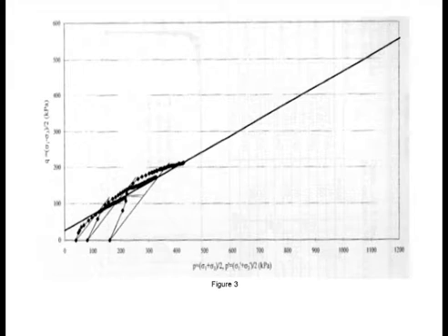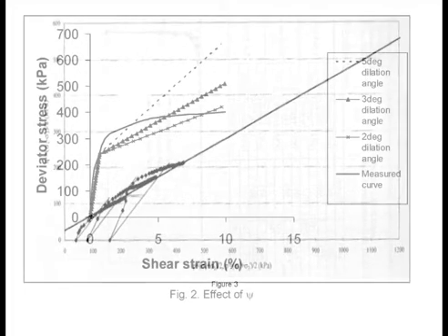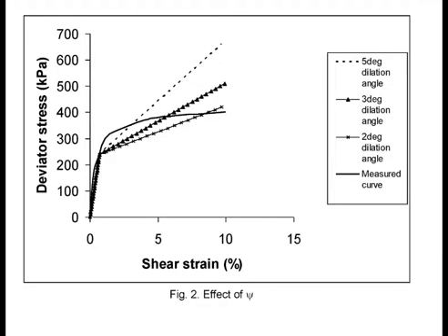So that is the radius of the Mohr circle at which the yielding takes place, the turning around point. I take it to be the yielding, because suddenly, from a nicely elastic stress path, it switches over to a plastic stress path. At that point, I take it to be the yielding U point. So when you look at the U point, this is the T value, which is the radius of the Mohr circle, 110. So the Q is twice that. When you look at the Q, I use 200 something. It's actually 2 times that particular value.